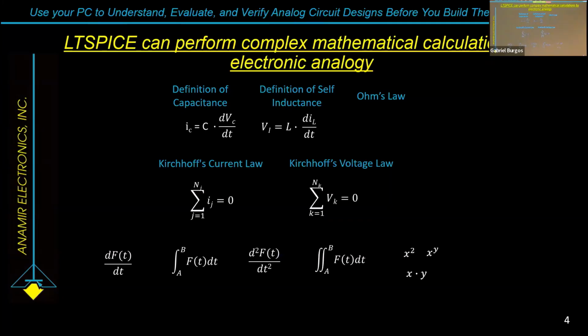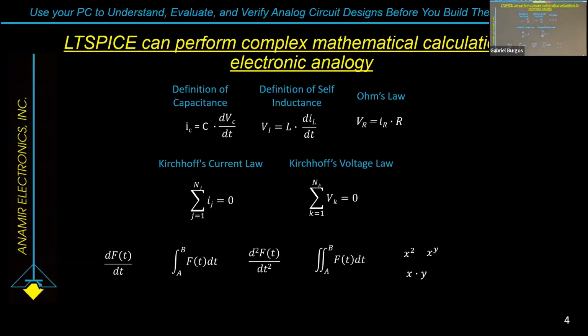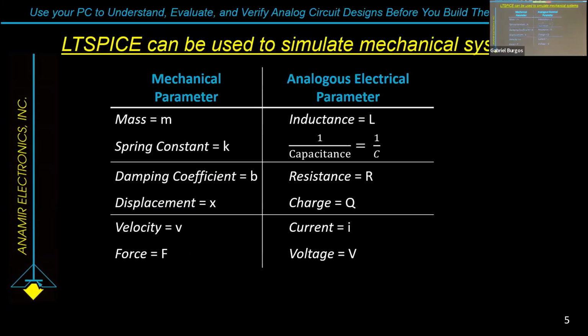And so anything that actually uses differential equations could be applied to LTSpice. You can actually use LTSpice to do a lot of things outside of electronics. You can use it to simulate mechanical systems. You just have to make the corresponding substitutions, mass for inductance and spring constant for something related to capacitance.